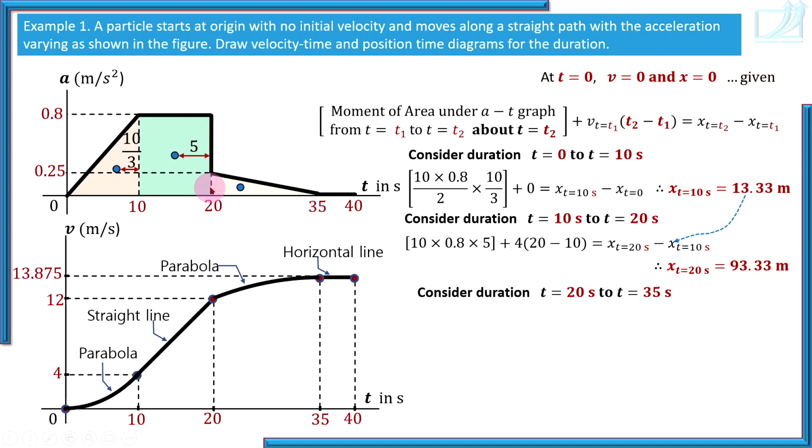So from its vertical edge, distance is 1/3 of the base. Now how much is that base here? 20 to 35, that means 15. So 1/3 of 15 from vertical edge of the right angle triangle. So 1/3 of 15, that is 5. 5 is the distance from that vertical edge of the triangle, but we want its distance from t equal to 35, and that is 10 cm.